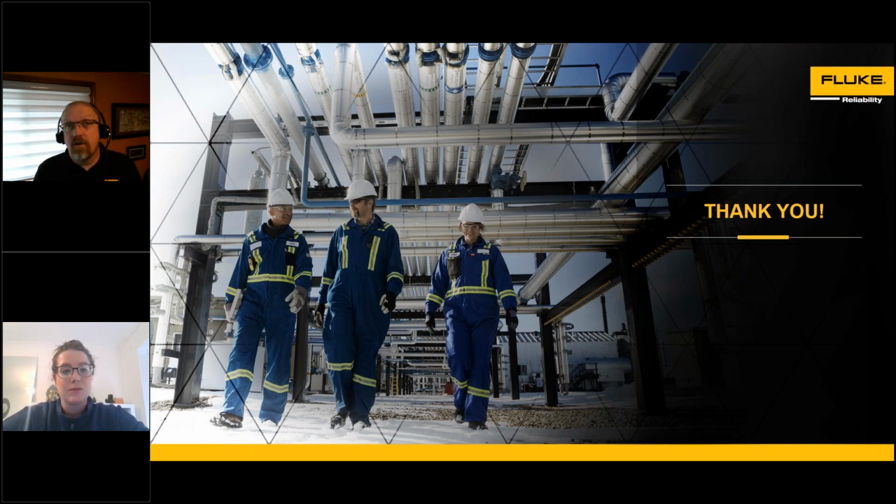So while you don't necessarily need to have an on-site vibration analyst, when you get recommendations from your wireless system or from your remote condition monitoring, somebody should go out and make sure that that's not something like a soft foot condition where a bolt has come loose and the shims have come free, or take their strobe out and have a look at the coupling and make sure that the coupling is still in good shape. So no, you don't necessarily need an on-site vibration analyst, but you do need to verify the data that is coming into you.